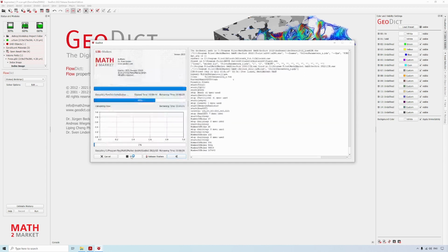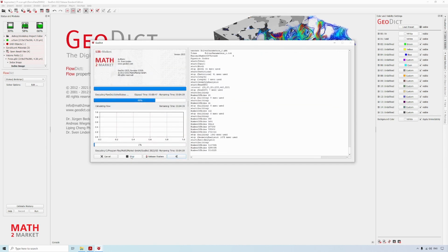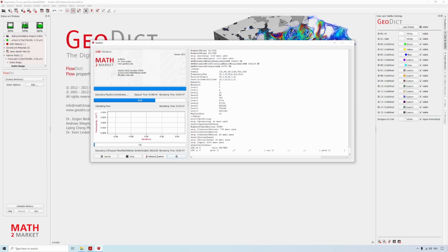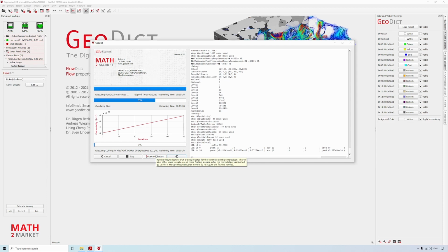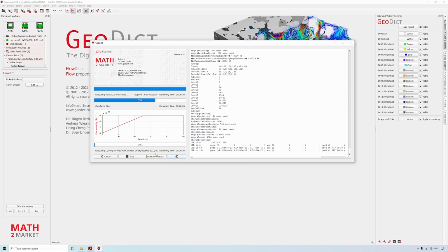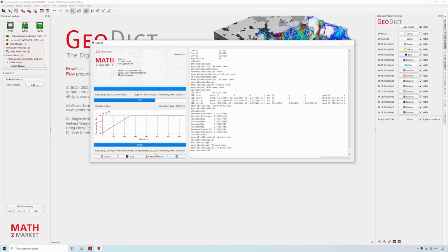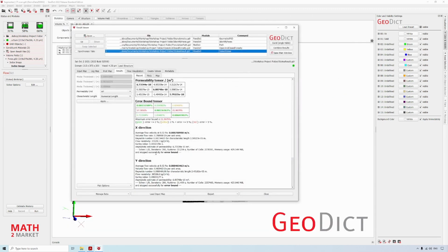And for everyone who is using a floating license and who is sharing this license with your colleagues, if you set up a simulation which is taking maybe 3 days on a very large structure, 2000 times 2000 times 2000 voxels, you can start the simulation and then select release floaters. This will release all floaters except the FlowDict floaters, so that the license is free for your colleagues to use while the simulation is running for you.